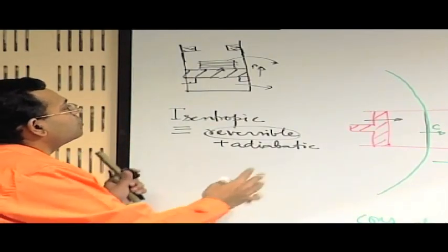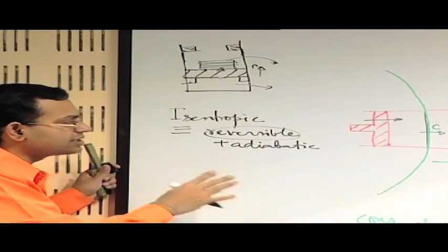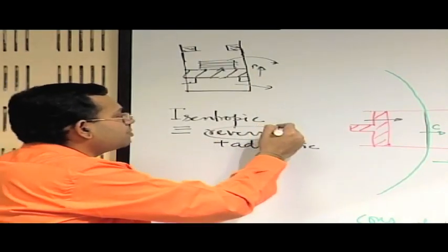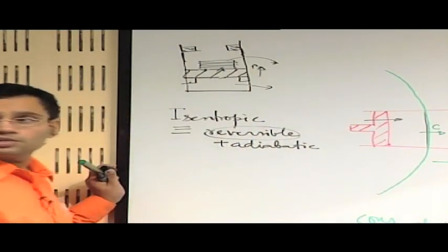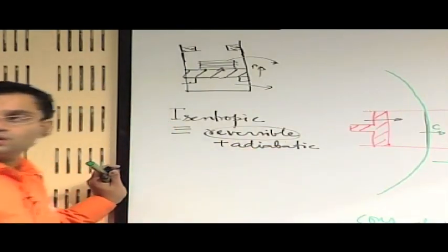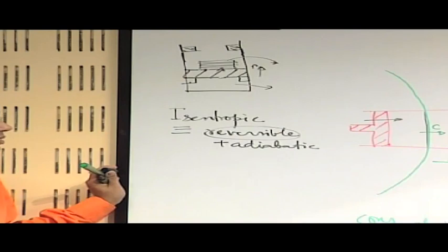in a way that we will not have enough scope here to discuss, but just keep one important thing in mind, that if you want to have a reversible flow or a reversible thermodynamic process, it should be devoid of friction, because friction is one thing that makes the real process deviated from a reversible one. So when we say a reversible and adiabatic process, we mean basically a sort of frictionless and adiabatic process and